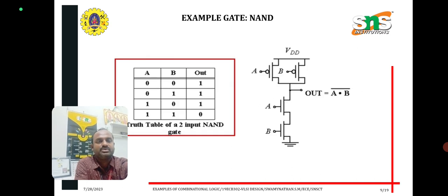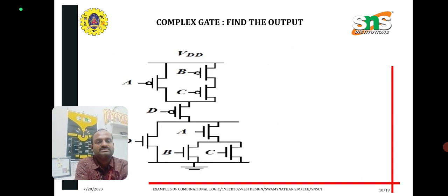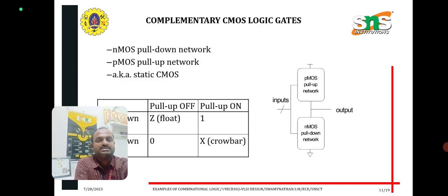If you think about the NAND gate, just remember the keyword dot NS. Dot NS means NMOS is series. If NMOS is series, PMOS is parallel. And next, the complex logic gates: we will discuss the combinational logic gates, OR and inverter, that is the complex logic gates.